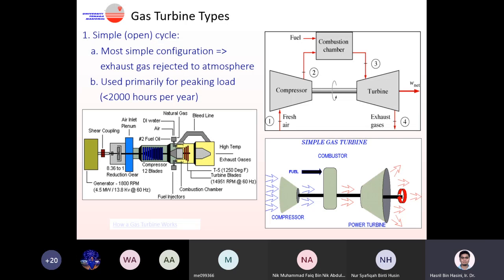And this exhaust gas, let's say for example we have methane combustion, natural gas. With methane combustion, the maximum temperature is around 2,000 Kelvin, 1,900 degrees Celsius as an example. That hot gas is used to drive the turbine. After the energy has been converted, the exhaust gas temperature should be around 400 to 500 degrees Celsius.